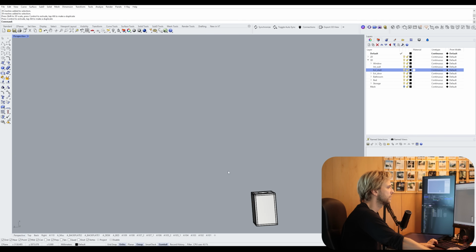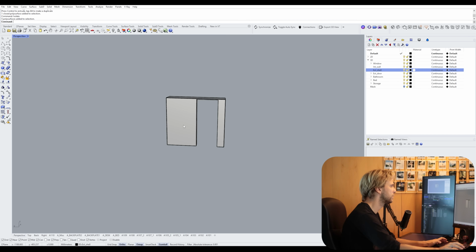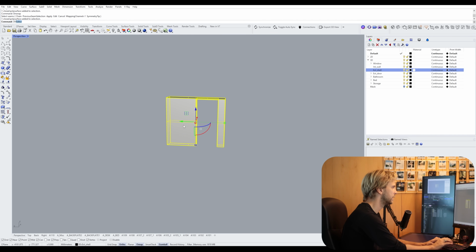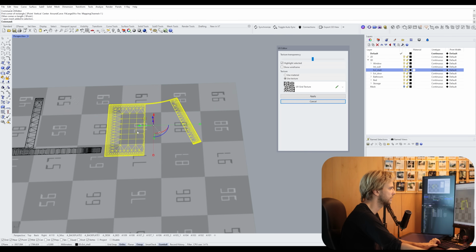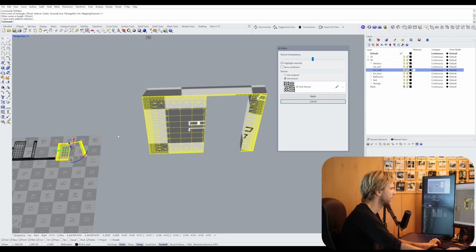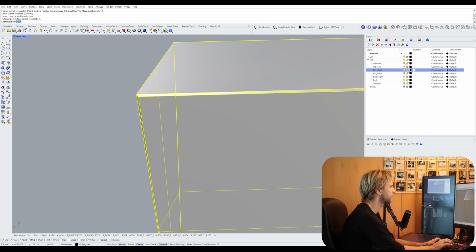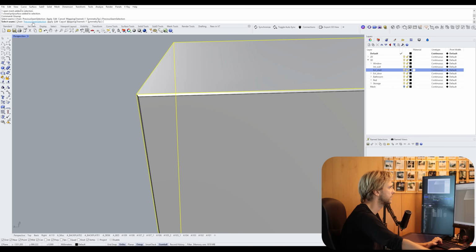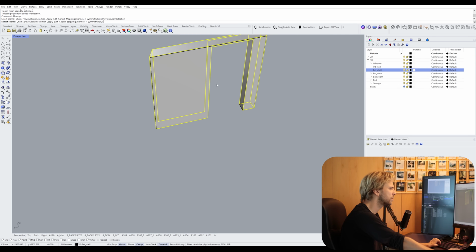So I'll hit cancel. I'll select the problematic shape. I'll isolate it and I'll unwrap it again. Not unwrap it, sorry, a UV editor. I'll create a UV editor just for this. Like that. Okay, so it is this island right here. Cancel that and let's see. Unwrap. Previous seam selection to see the seams. And let's try to visualize how this would unfold.